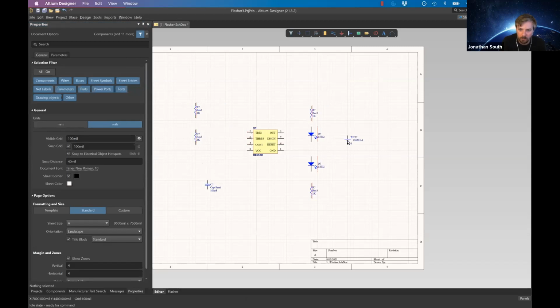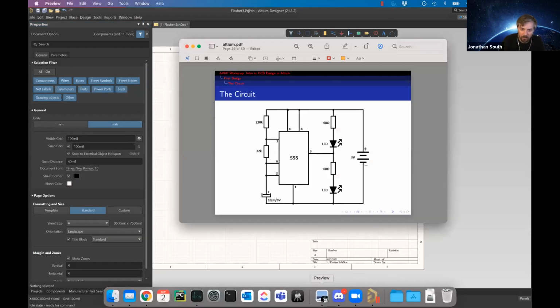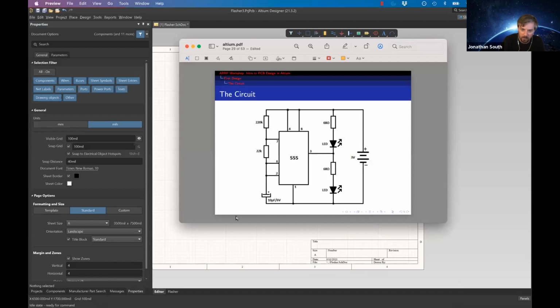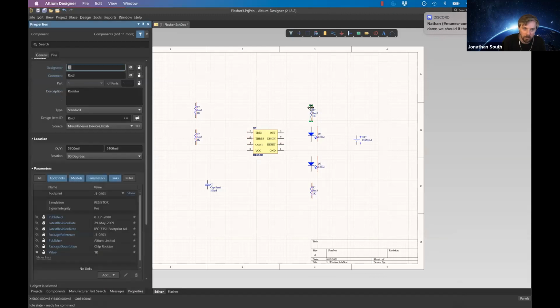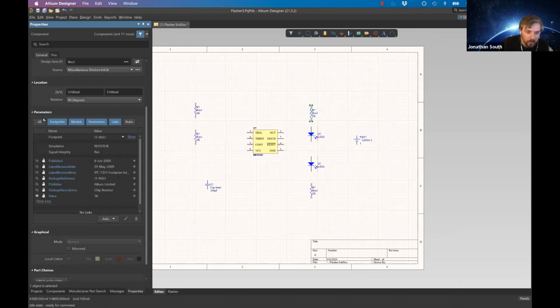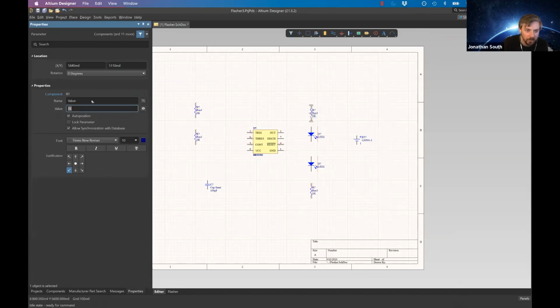Okay, so there's my rough circuit schematic. It's not going to be the prettiest or most optimized thing in the world, but that's my layout. I'm going to do component values next. So 68 ohms on the LED resistors. So obviously you want to open up your properties. And then where do we do the value? Should be somewhere. Do you just click on the, I haven't used Altium in a while, so sometimes there it is. So clicking on the 1K portion that comes up, you can change the value.